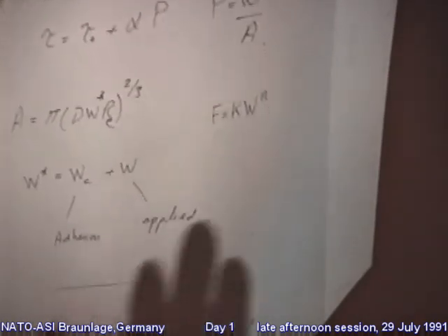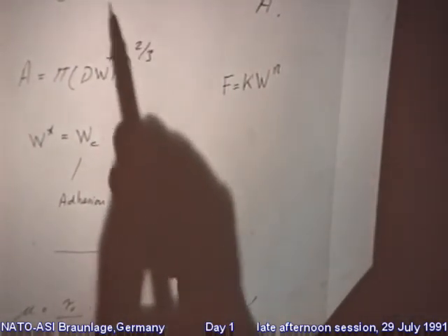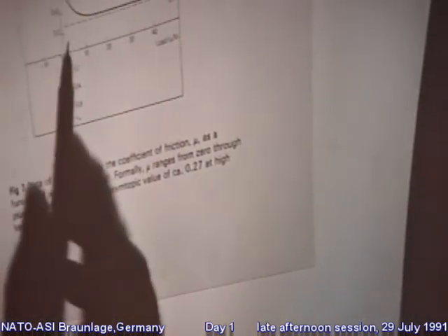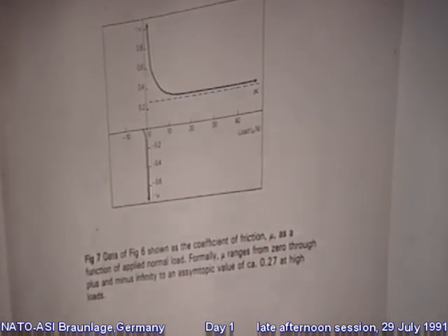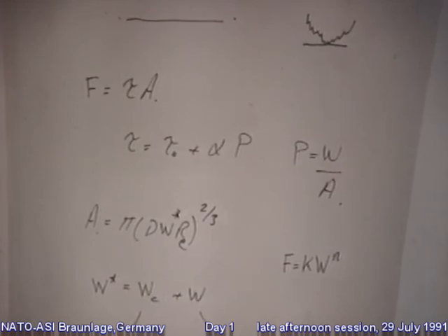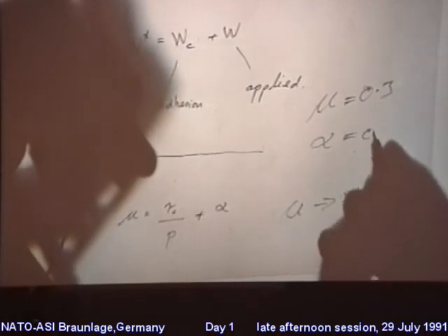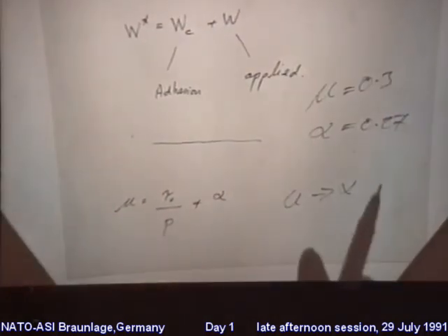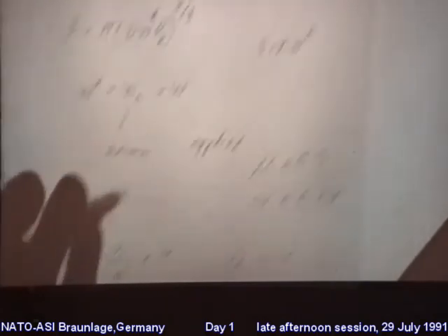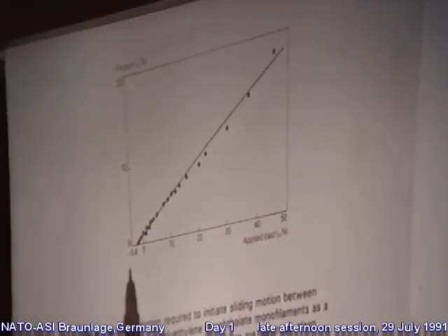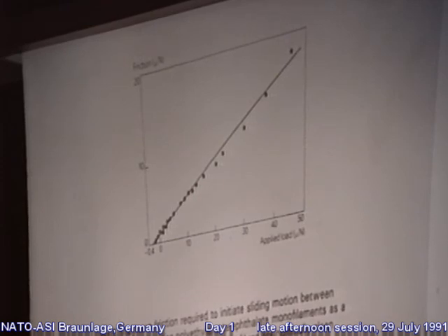And someone, it wasn't me, chose to measure the pressure coefficient of interface shear stress of pork fat. So he could compute the upper limit of the coefficient of friction from this curve here. And it turned out that the coefficient of friction that Coulomb had was, I think it was about 0.3, and the pressure coefficient of pork fat thickened with lime was about 0.27. So the point I wanted to make was that it isn't necessary to account for this autoadhesive load component via a convoluted argument. You can just simply add it, and I think quantitatively that's correct.